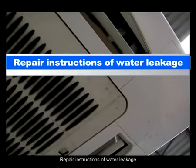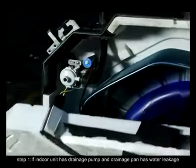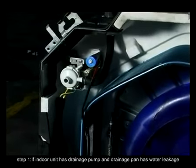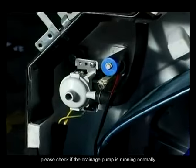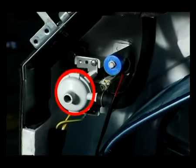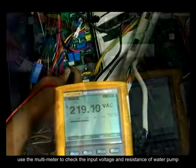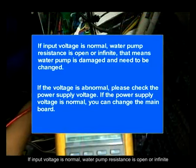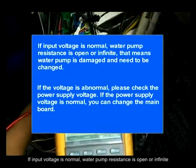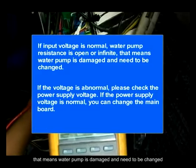Repair instructions for water leakage. Step 1. If the indoor unit has a drainage pump and the drainage pan has water leakage, please check if the drainage pump is running normally. Use the multimeter to check the input voltage and resistance of the water pump. If the input voltage is normal but the water pump resistance is open or infinite, that means the water pump is damaged and needs to be changed.